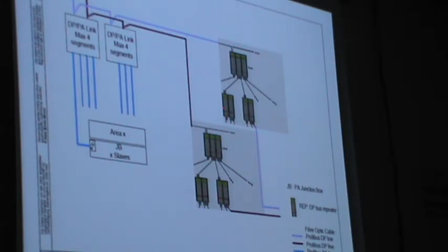But for the transmitters, instead of giving power supply from a different source, we use only the one inside the DCS. So you have the power hub here. From the power hub only, you will get these 4 cables out. These always have a 24 to 30 volt power supply, and this will be connected to your JB.